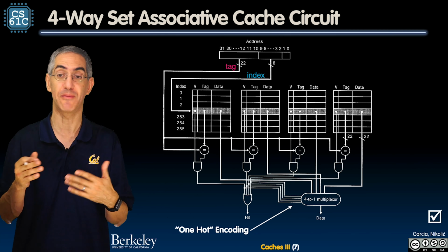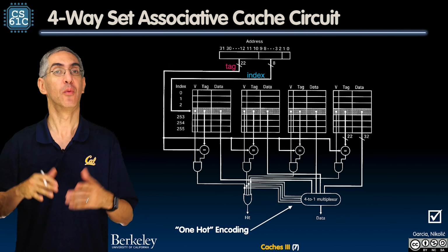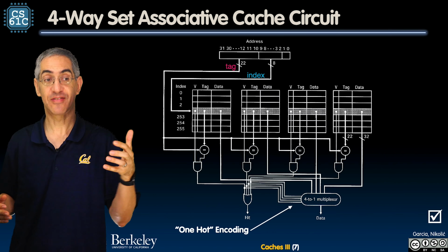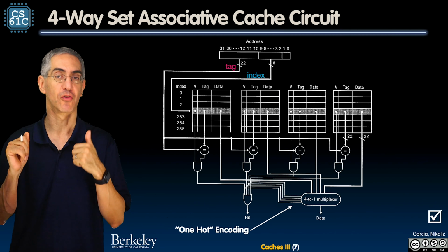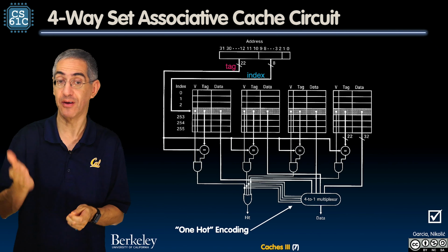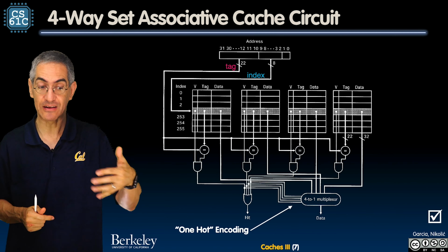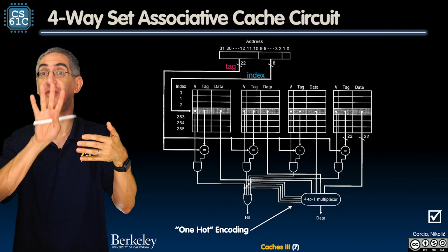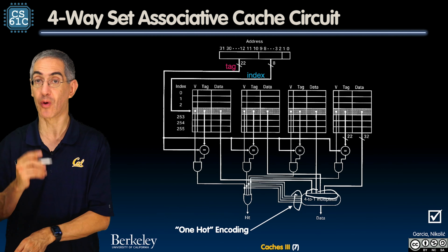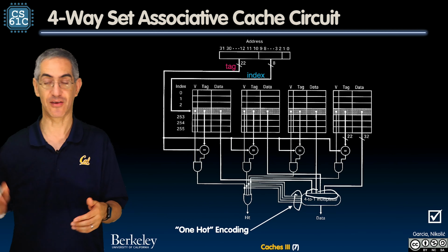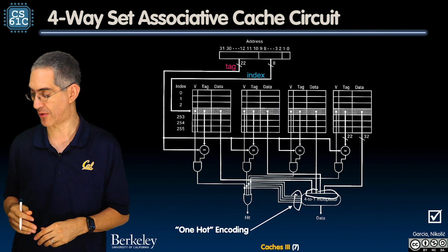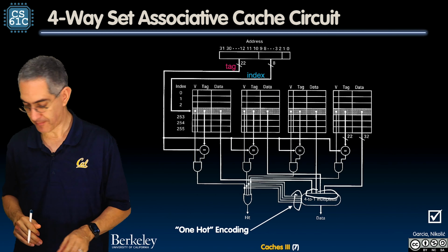And I do encourage you to sit back. It might be on a final exam where you might have a situation where I ask you to tell me how to build a one-hot signal line for a 2-to-1 mux, or a 4-to-1 mux, or an 8-to-1 mux. Think about how you do that. By the way, just in general, if I have a one-hot line, I have to have the number of control lines equal to the number of input lines. So notice I have 4 here, 4-to-1, and I have 4 of these, because only one of them is going to be hot, and that one drives the guy that ends up driving the bridge. We always talk about this being a bridge, and it's like 4 roads converge on 1 bridge because the bridge is out, or they're repairing a side of it. So that's the idea, okay?